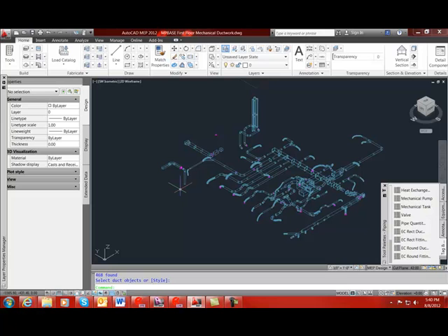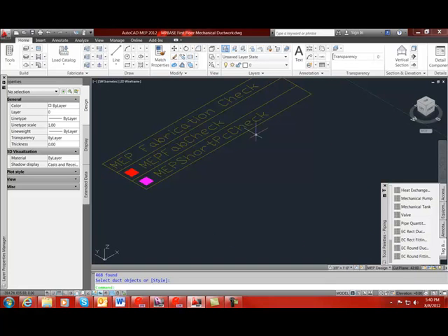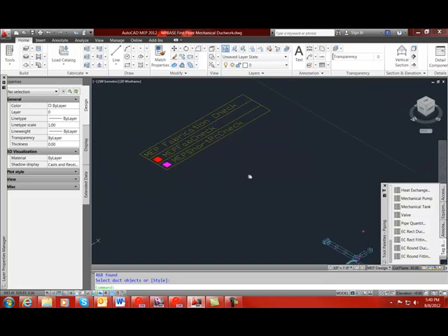Alright, now to eliminate short pieces, use the MEP FabCheck display theme again, specifically the short piece checker portion of it, which is right here. This marks pieces of duct under 12 inches pink and fittings under 4 inches pink. This makes it very easy to spot short pieces and fittings that need to be either removed or flexed.